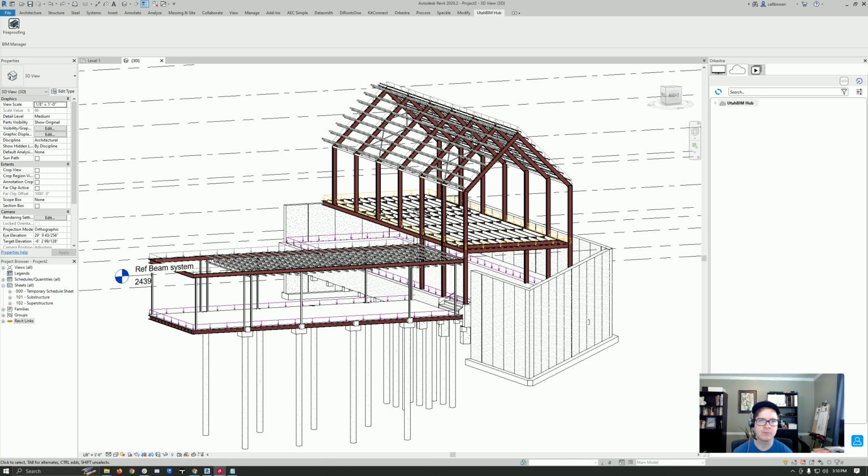To be able to run our hub, you'll need to download Orchestra. Once you have that installed, you synchronize your Orchestra plugin with our hub, and that pulls in all of our Dynamo scripts that you've subscribed to. Then you hit synchronize here, and you hit refresh content and quick access. The quick access creates these buttons here on the top left, which is the Dynamo script. That's all you're going to do, is click on that, and there's no crazy Dynamo spaghetti monster that's going to come and get you in the middle of the night. You don't have to deal with all the code. It gives you a couple of inputs, you select what you need, and it runs.